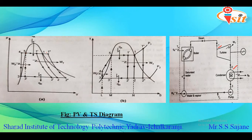Now there is one more important point that we can see in the PV and TS diagram: there are three different lines representing the turbine process. That is, process 1 to 2, as well as 1' 2', and 1'' 2''. These three lines denote what kind of steam is provided to the turbine. If we have wet steam, it is represented by 1' 2'.